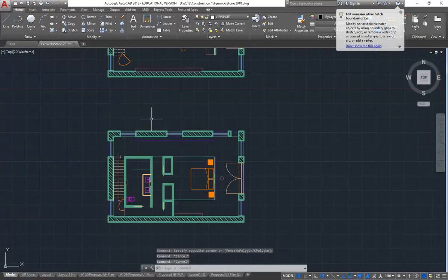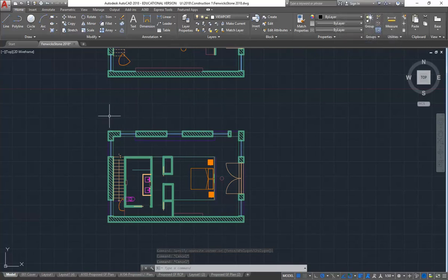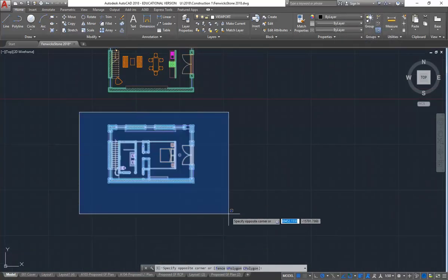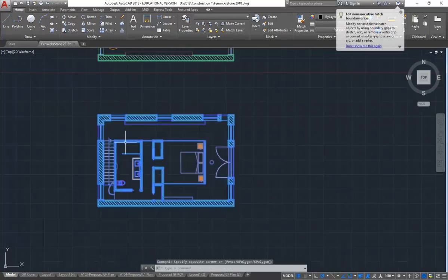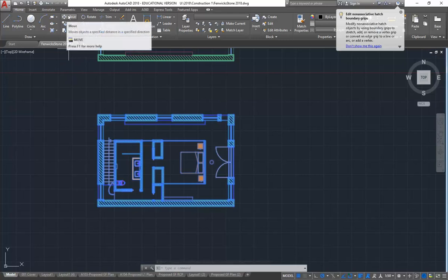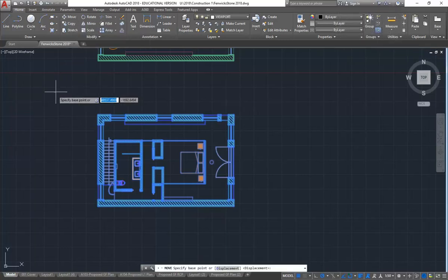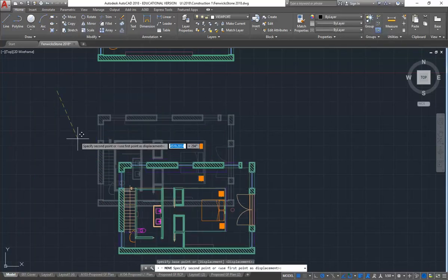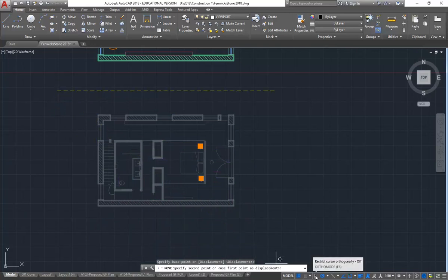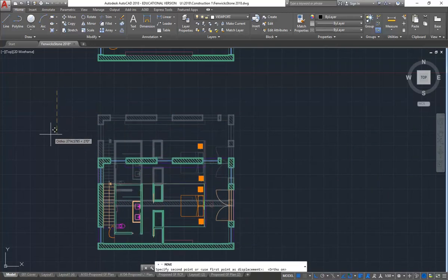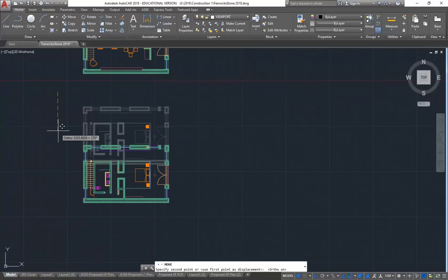So is it going to fit? If I draw an elevation up here, it's probably not yet, so there's not enough room there. So I'm going to select that whole drawing, or that plan, and then I'm going to use the Move tool, click a base point, and then with Auto turned on, bring it down, and I'm going to type in a round number.